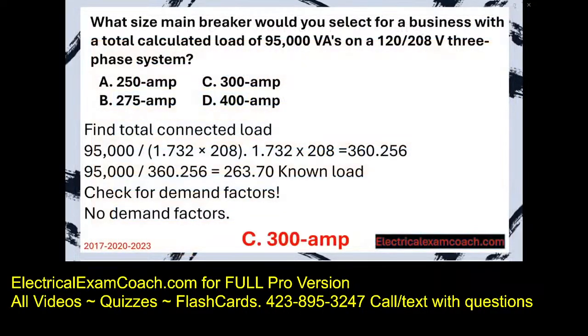We're going to now put this on a 300 amp breaker instead of, like in the previous question, it would be on a 400 amp, meaning that we'd have to have larger wire in the previous question, which may lead us to have larger pipe, which we may end up with a larger cost of overall project. The beauty of three-phase is the numbers come down. So this one's on a 300 amp service, which means we can put it on smaller wire, which might mean we can put it in smaller pipe, which might end up having a smaller overall cost.